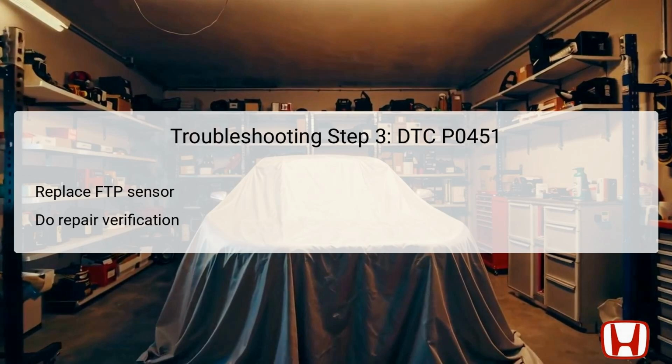Following the replacement, it is necessary to perform a repair verification process. This verification step is crucial, as it confirms the effectiveness of the repair and ensures that the system is operating correctly post-repair. Monitoring the OBD status again with the HDS will help confirm whether the issue has been resolved and if the vehicle is performing optimally, with no further DTC P0451 indications.